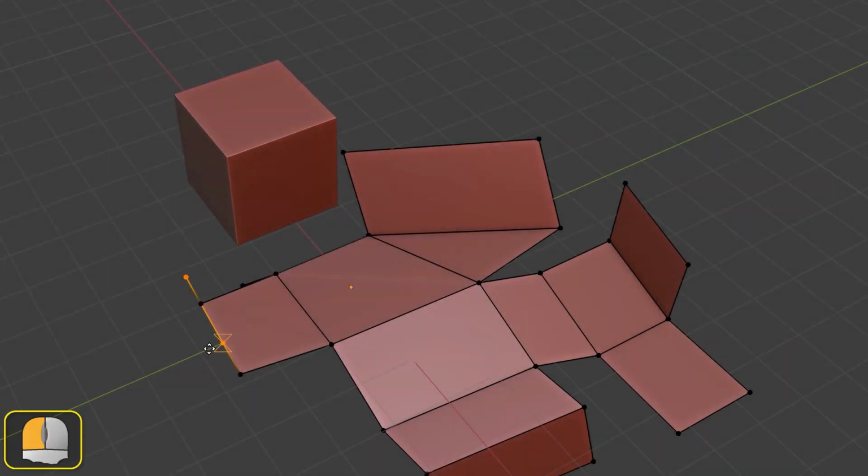Let's watch that again. We start the drag as usual. Then press the B key. This causes the edge we are moving to jump back to its original position. With the left mouse button still held down, we'll see the snapping positions highlighted with their appropriate symbols.